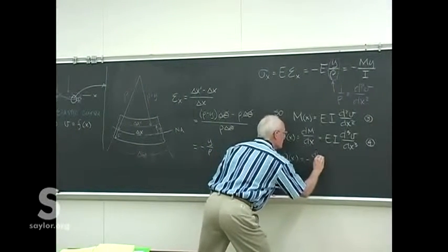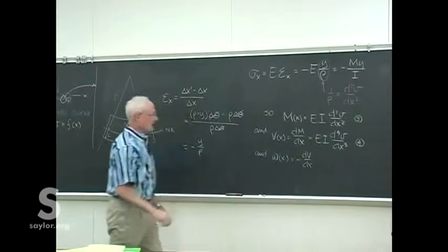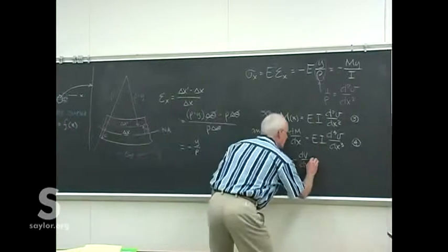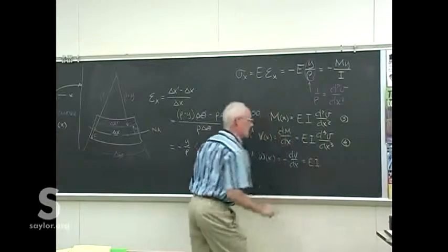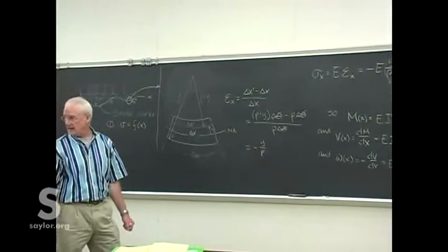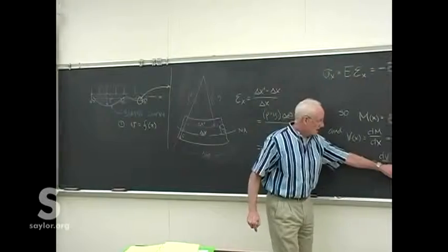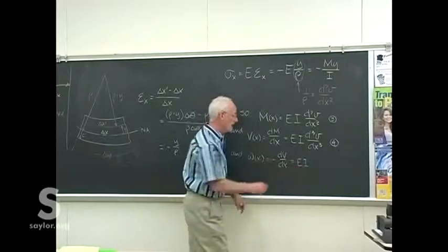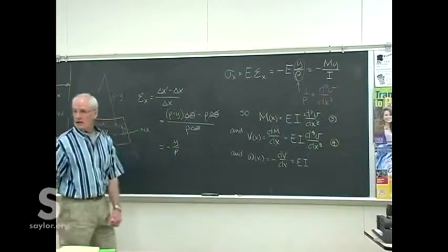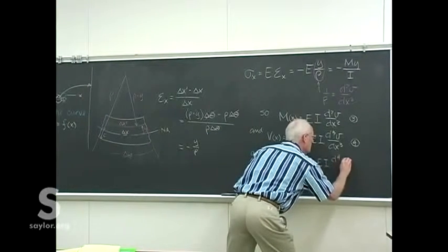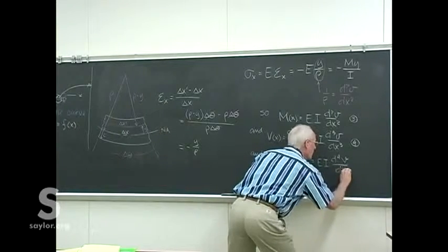And if you remember, there's a minus sign in there because a downward load we consider to be a positive load, because that's what most loads are. And then that, of course, is this quantity EI. And remember, that is completely load independent, that E times I. E is a function of the material of the beam itself, whatever material was chosen for the beam, and I is a function of the geometry of the cross-section. So those two things are completely load independent, which is why we typically pull them out.